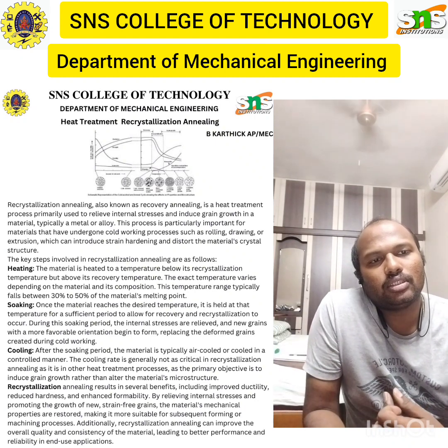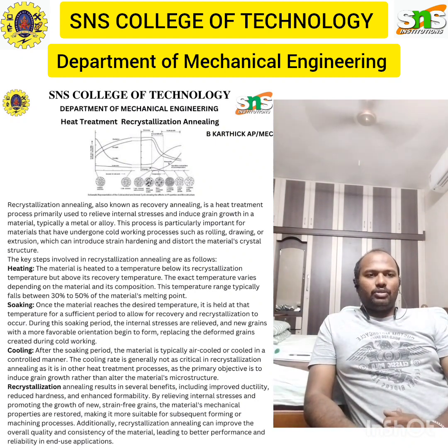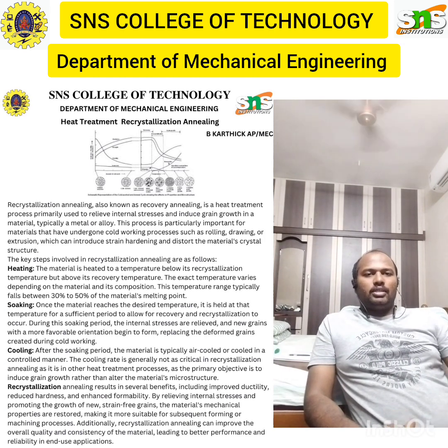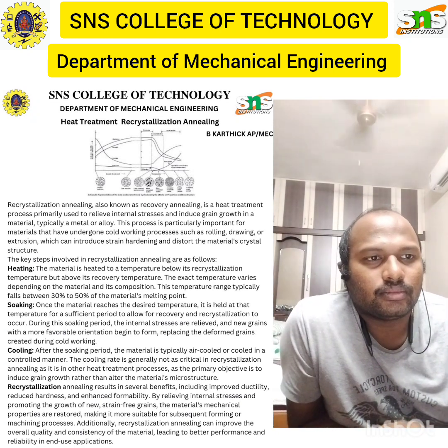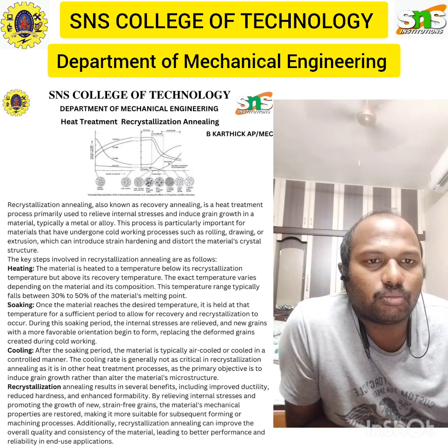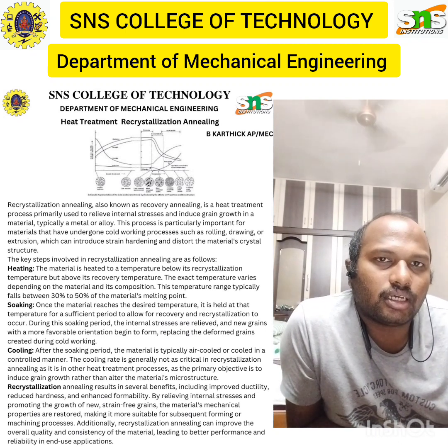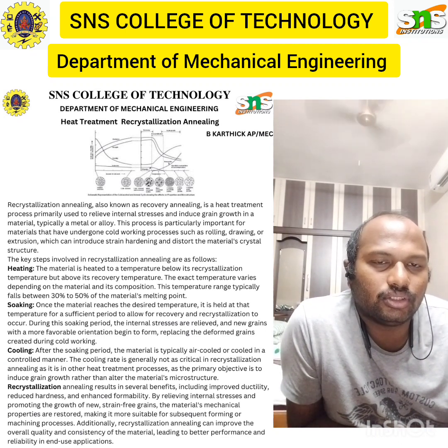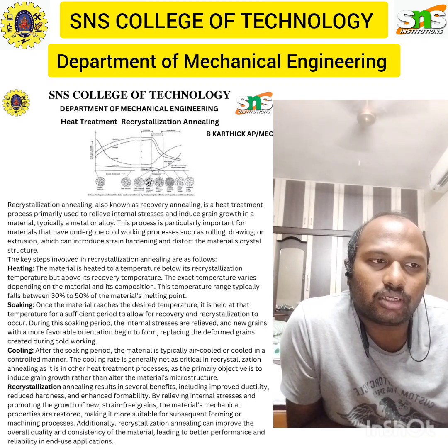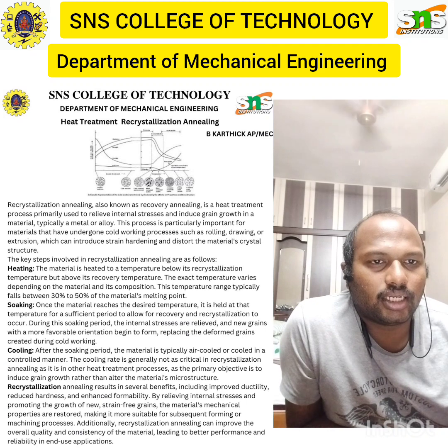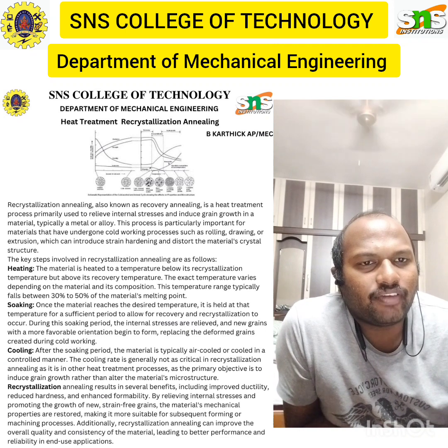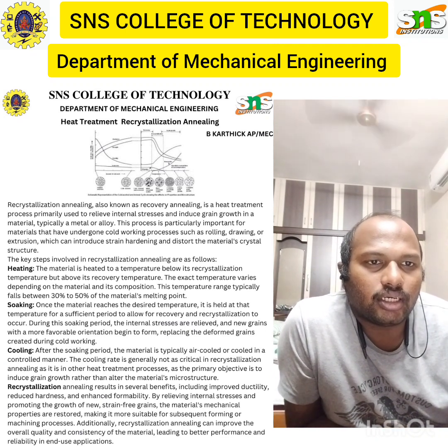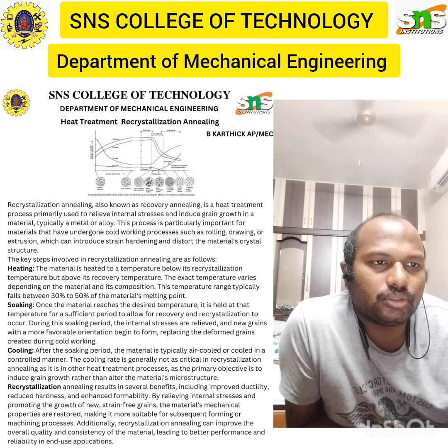hardness. The round carbides formed during the process are less abrasive than the original carbides, making the steel easier to machine. Additionally, the softened steels are more ductile and less prone to cracking or distortion during subsequent forming or machining operations. This spheroidizing annealing is commonly used in manufacturing precision components such as bearings, gears and cutting tools, where tight tolerances and excellent surface finishes are required.